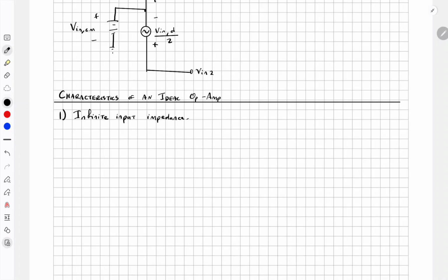I will draw a very large op amp triangle on the right. Okay, and our input 1 goes here, it has the positive sign, and then input 2 goes here and has negative, just as before. What we mean by infinite input impedance is that it's an open circuit between 1 and 2. Open circuit means that R in is equal to infinity, right?